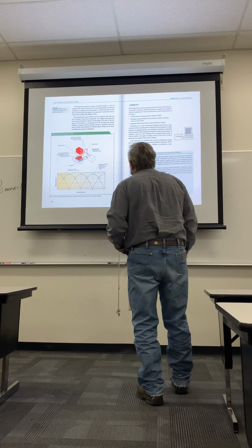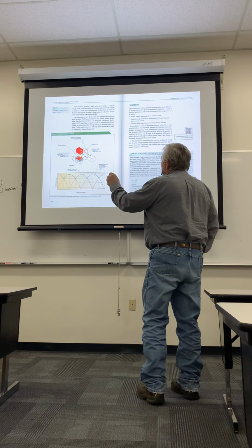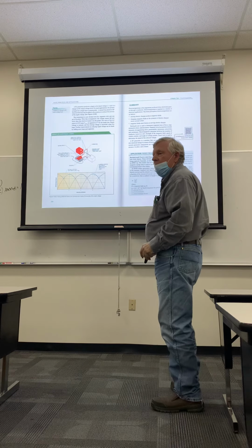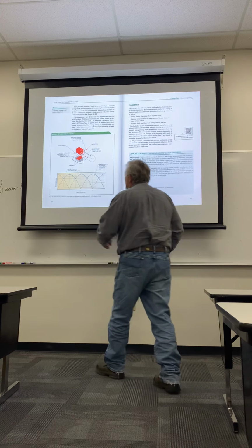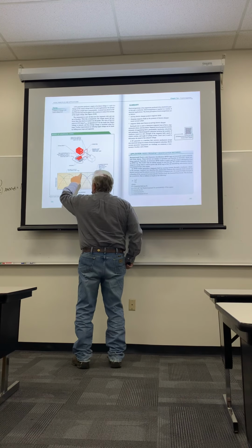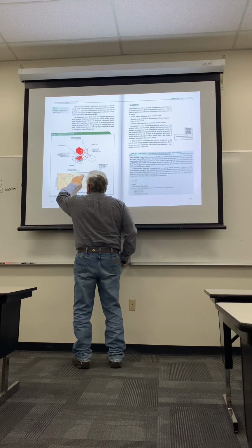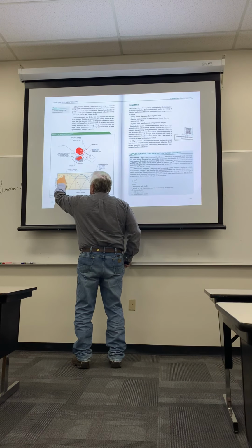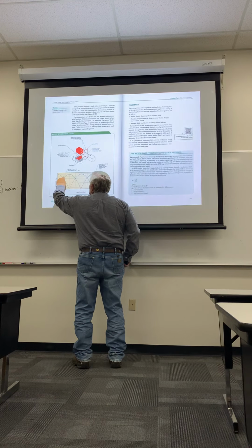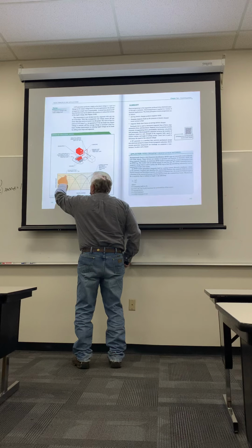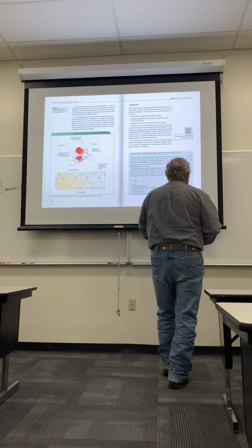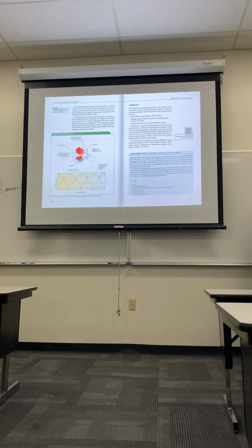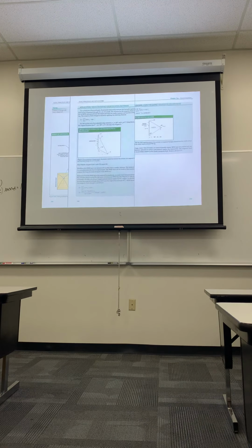Doesn't really end there, because we could actually put more conductors in there to turn through there, and we could actually end up with 3-phase. With 3-phase, you have even less distance between these maximum outputs on this sine wave, so there's less space in here where whatever appliance is being used sees that drop in voltage. It will see it much less as we stay in this area right here all the way across with another commutator ring there. Could you just put more wires in to make it smoother? Yep. Up to a point.